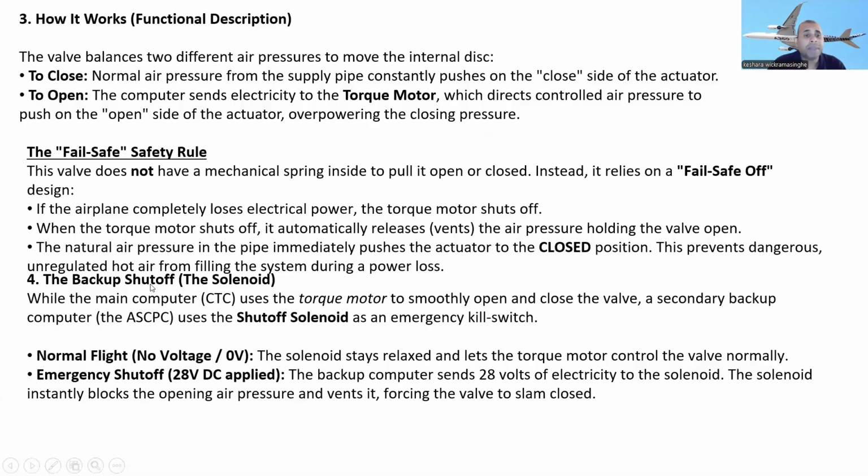Okay, so the backup shut off solenoid: the main computer, the cabin temperature controller, uses the torque motor to smoothly open and close the valve. The torque motor is the one we use to smoothly open or close the valve. The secondary backup computer uses the shut off solenoid as an emergency kill switch. Normally the main computer uses the torque motor to open or close the valve smoothly, but the secondary backup computer, ACPC, uses the shut off solenoid as an emergency kill switch.